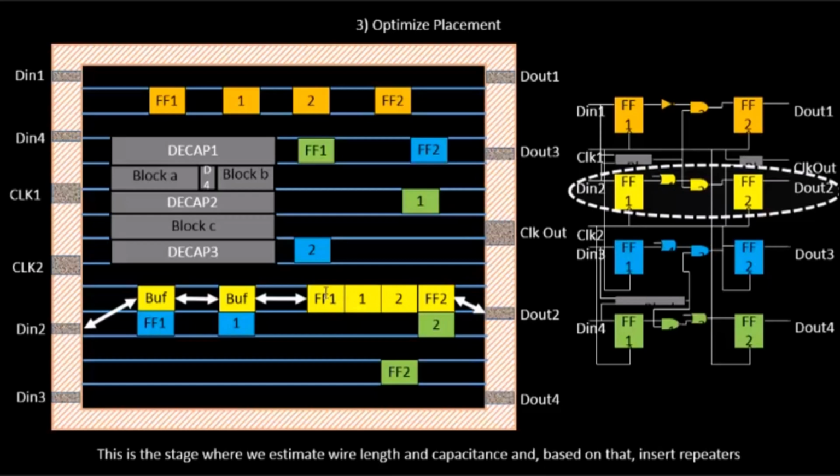One of the reasons is, let's say this particular section of your circuit works at very high speed. In that case, we bring those sets of logic very close to each other and make sure that there is zero delay when sending the signal from flip-flop 1 to flip-flop 2. Let's say this works at 2 gigahertz or something. In that case, we don't want to waste delay on the wires, and as a result we have abutted these cells.